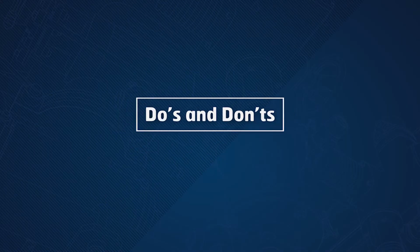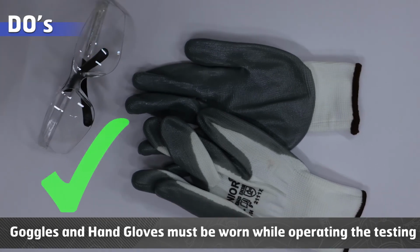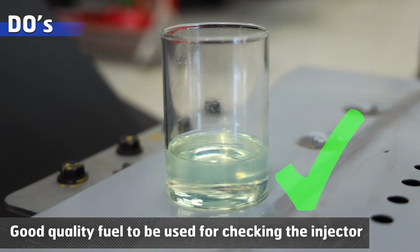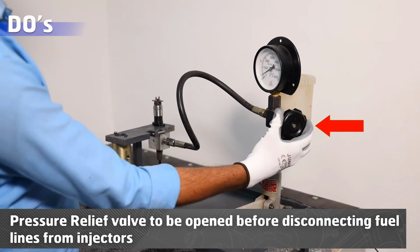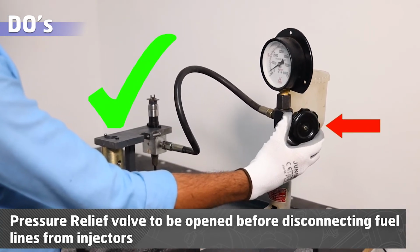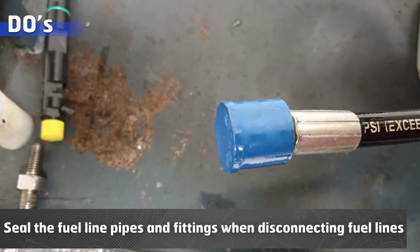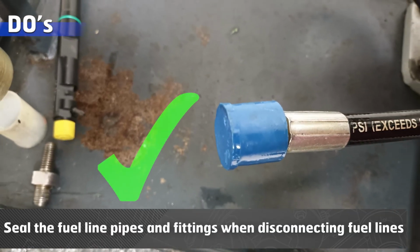Do's and don'ts. Do's: goggles and hand gloves must be worn while operating the testing. Good quality fuel to be used for checking the injector. Pressure relief valve to be opened before disconnecting fuel lines from injectors. Seal the fuel line pipes and fittings when disconnecting fuel lines.